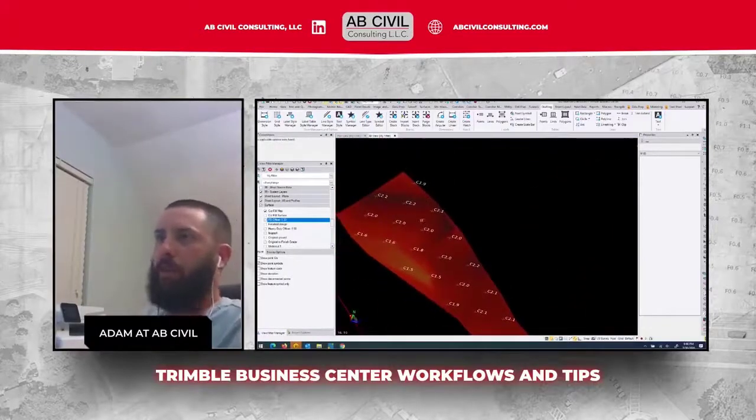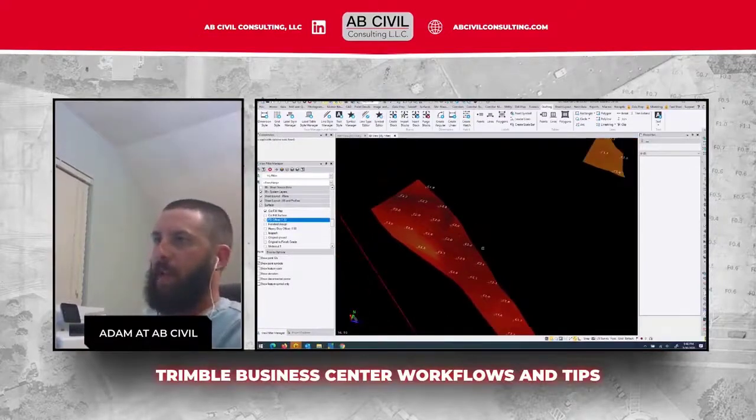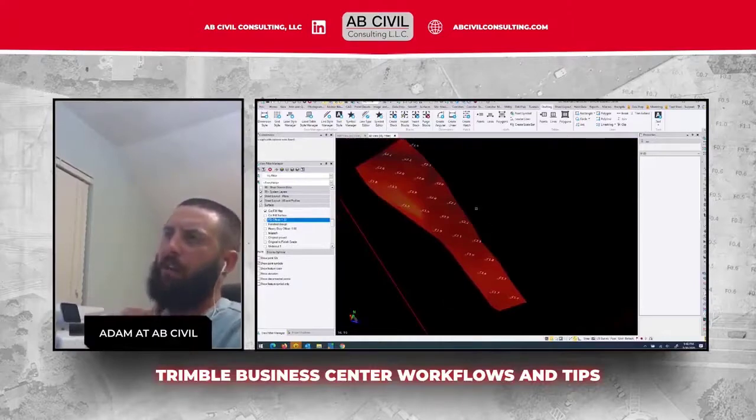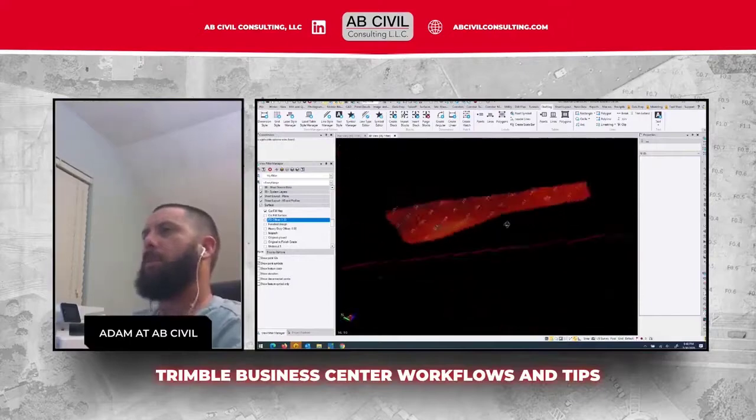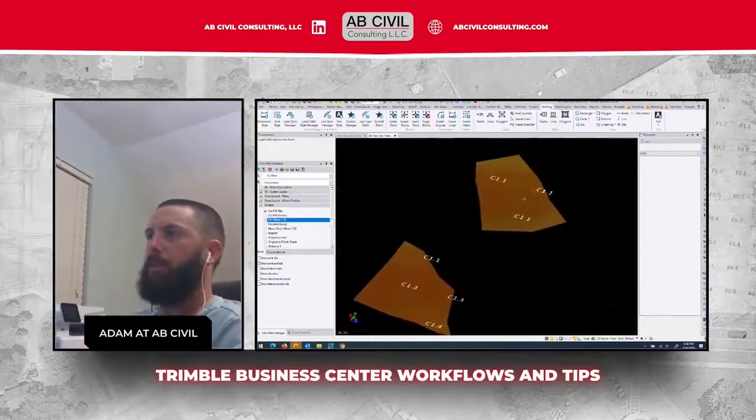So in this case, the contractor went in, they cut down to subgrade, they got ready to start placing stone, and they said, this doesn't look good. They went to the owner. The owner looked at it and said, yeah, cut 2 feet out, cut 1.5 feet out, or they probably just chased it out until the unsuitable was gone. And they could tell it was good material, so they cut it out. And this represents that because they did a topo in the field.